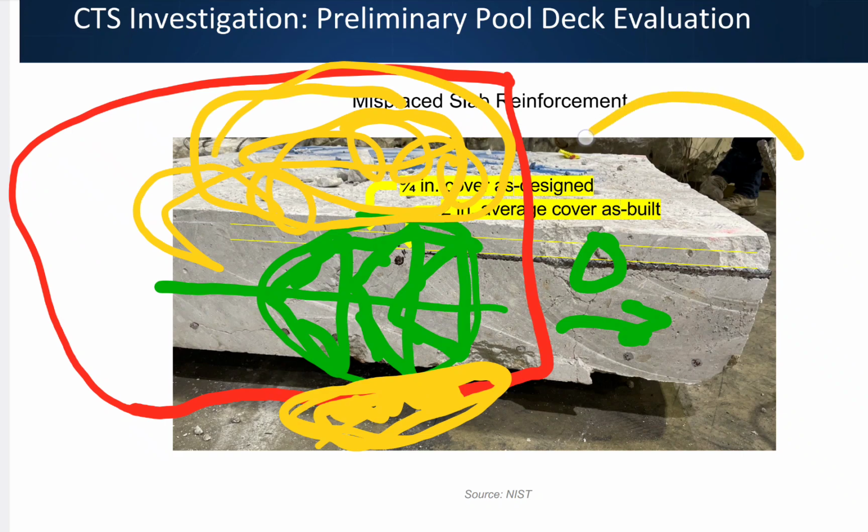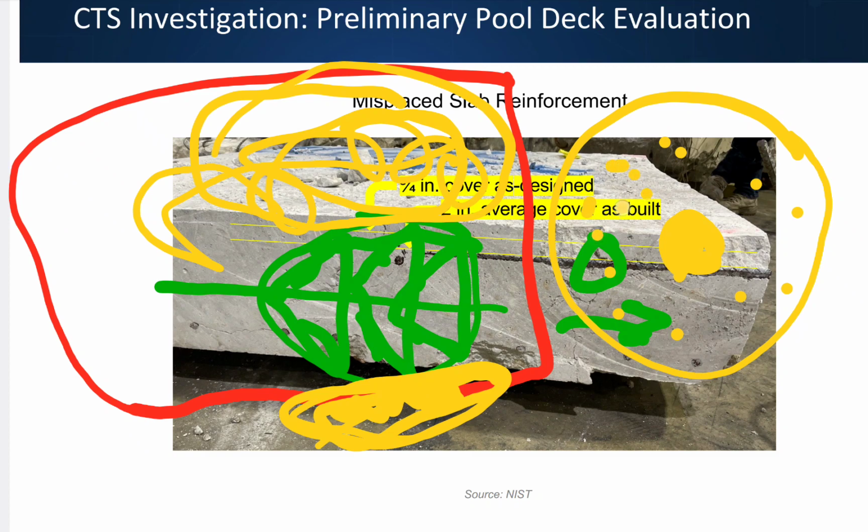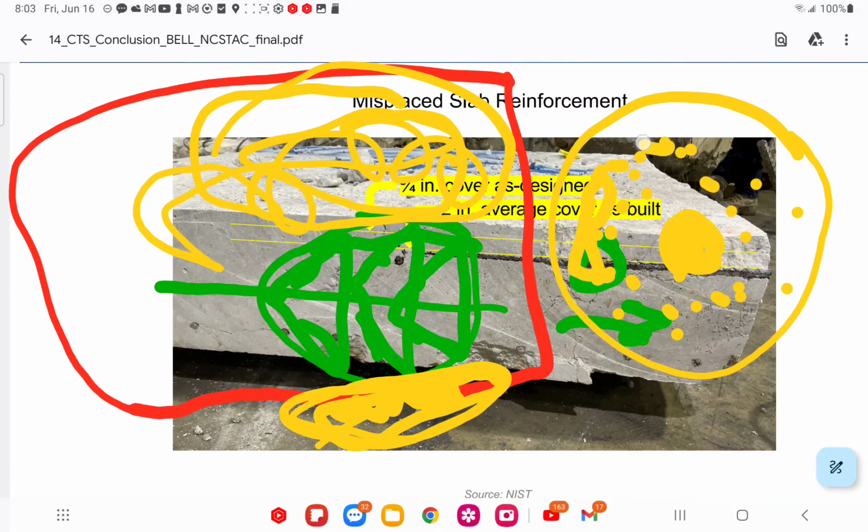So what the studies show is that if this is your concrete and this is your rebar in the middle, the greater the PSI out here, the stronger the bond on the steel. If you were to use sand and plaster to hold this in, it wouldn't be a great bond. But if you use 8,000 PSI over 6,000 PSI, same for same, you'll get a stronger deck with the higher PSI. It acts like it locks in. The 8,000 locks in better. So this becomes a stirrup, if you will, around your steel, your rebar.